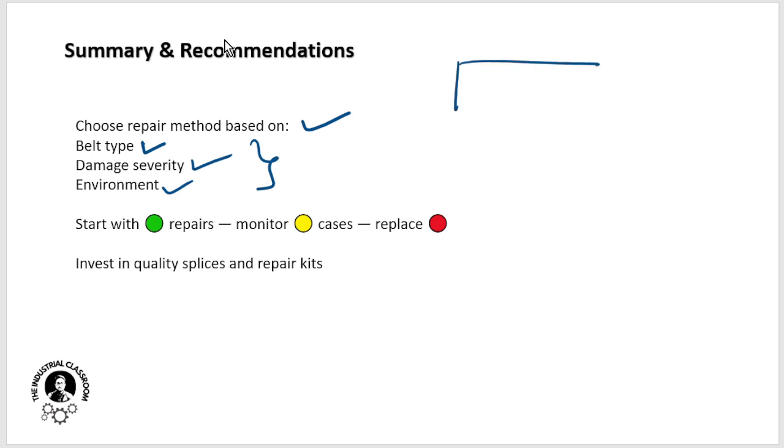For example, see, this is a conveyor belt, and then there I have added a cold patch here. But I know that it is a very moist environment. It will not sustain. Cold repairs will go out. Okay, we will again need to repair it. This will be a tremendous task. So in these conditions, we generally prefer mechanical joints, or sorry, mechanical repairs or hot repairs.